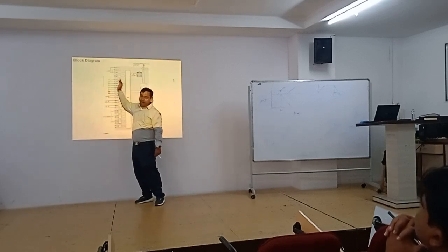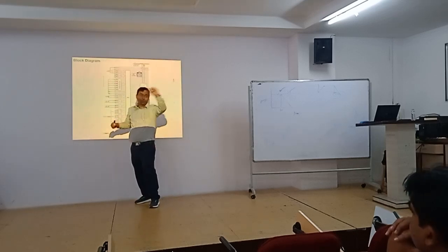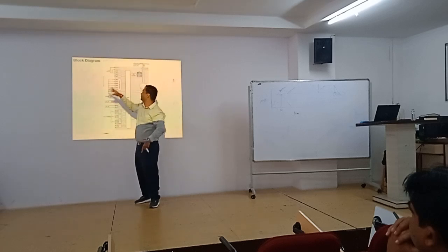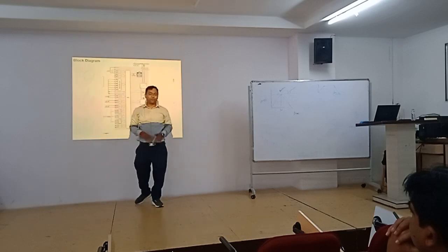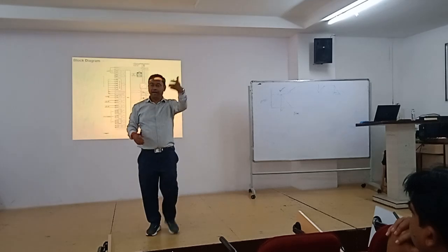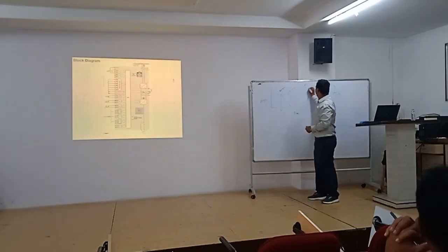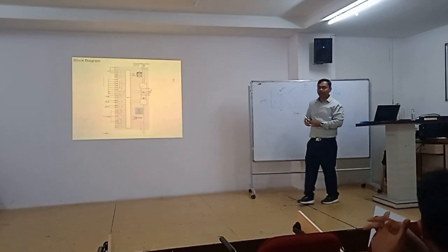So to give the start stop command, PLC output will be input to this and it will operate it. Similarly, to give the frequency, we have an analog output of the PLC and an analog input of the VFD. When you give a 0 to 10 volt output from the PLC, that will act as input to the VFD.